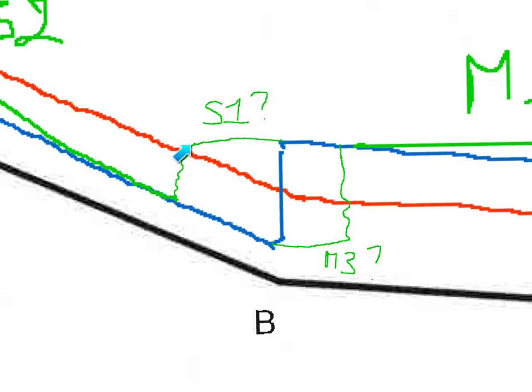Now, we know that we would have to have an S1 forming here, so increasing in depth and joining this normal depth here. So this depth just on the other side of the red line would have to be less than this depth here. And remember we've got very exaggerated bed slopes here, so we shouldn't be put off by that. In practice these are relatively flat, and over a short distance they don't have too much influence on the problem.